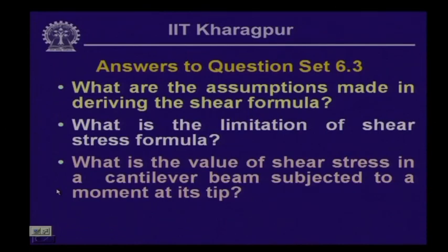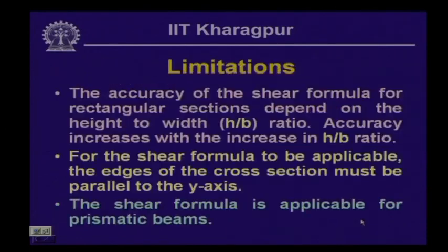Now, what is the limitation of the shear stress formula? You have seen that while calculating the stresses in a beam due to the shear force, we have used the shear formula, which is V Q over I b, and consequently we calculate the shearing stress at any point along the depth. Now, is this particular formula applicable for all kinds of beams, or are there certain limitations on that? That is what let us look into.